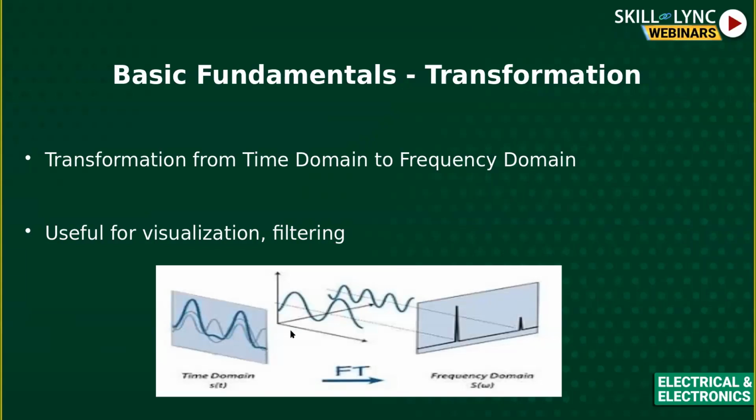Now, for example, you're designing an electronic device, okay, and it works perfectly fine outdoors. But when you get it indoors in your house, you see some kind of random noise appearing, okay, and then suppose you do a frequency transformation from time domain to frequency domain, you see that there is a small spike like this appearing at say 50 hertz, and only while operating inside the house. Now, based on this information, you could interpret that this is happening because of some kind of interference from your main power signals, like the AC frequency at your house is 50 hertz, right?